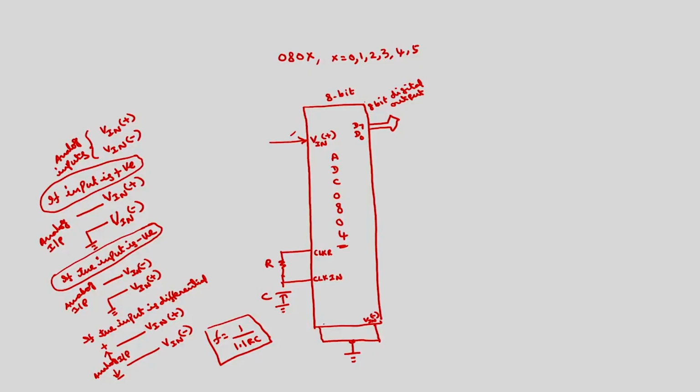Similarly, there is a chip select signal that also has to be grounded. In order to perform any operation, chip select has to be grounded. This is the chip select signal. This also I am connecting to common ground. And we have the read bar signal. This also has to be grounded for read operation. Whenever this conversion is over, we have to read the digital data here. For that, RD bar should be 0.